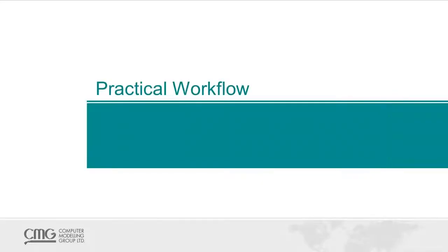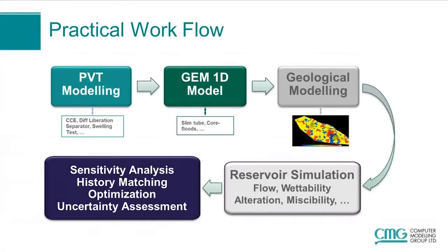Back to you, Hussein. So as I mentioned, you need to know what the practical modeling workflow is to replicate the field behavior. So here you will see the workflow. The first step is to create a PVT model based on the lab data, such as CCE and differential liberation. Then you need to use this PVT model in GEM to match the slim tube test results or the core flood test results. When you are matching the core flood test results, you can come up with some unknown parameters for the reservoir, such as relative permeability curves.